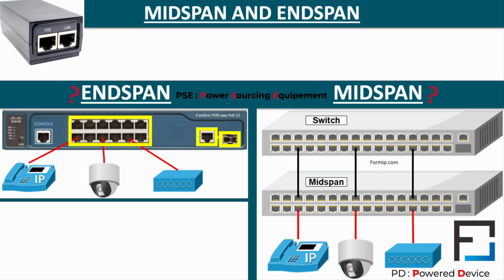So, is it better to use mid-span or end-span? With a mid-span solution, the disadvantage is that you have two devices to manage: the switch and the mid-span. You will therefore need to provide additional space in your rack. And what's more, the more devices you have to manage, the greater the risk of failure.